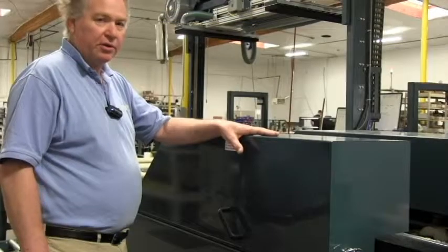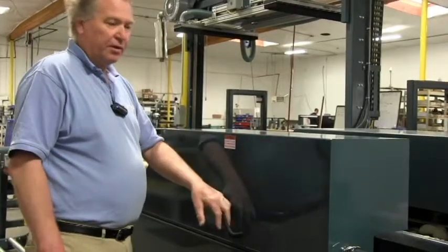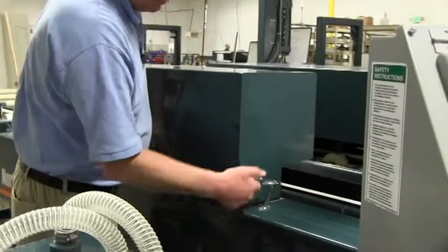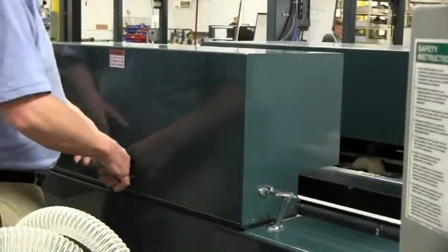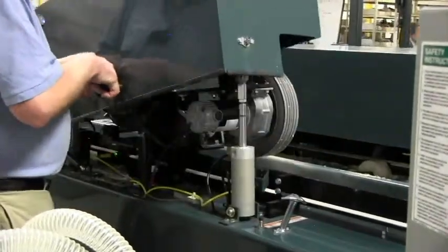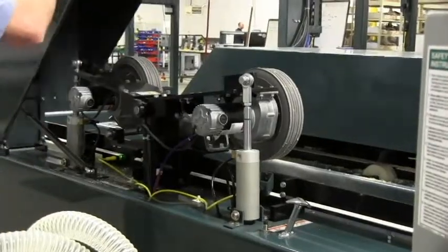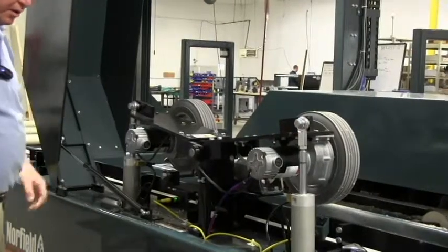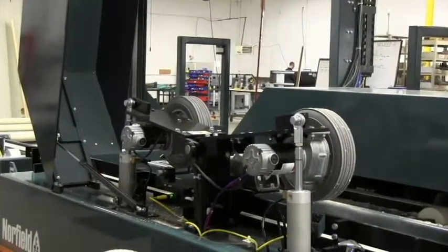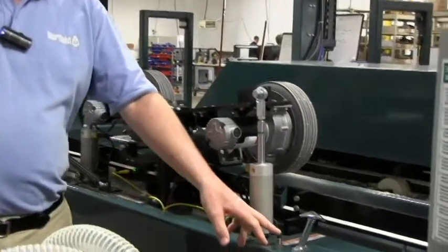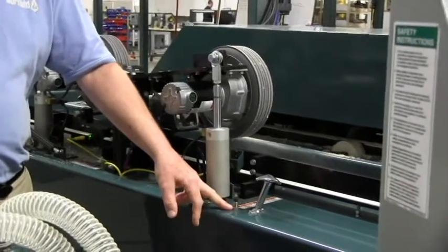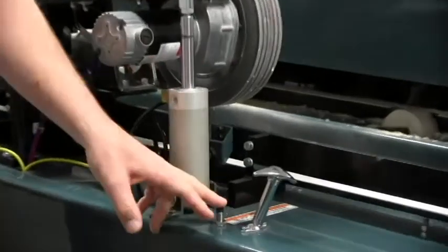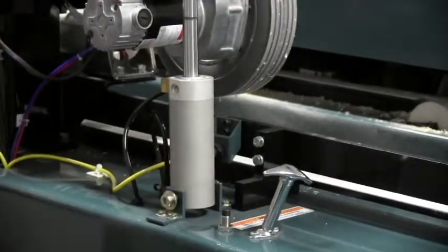You'll need to open the hoods on the Sizer. That's for cleaning or maintenance. So we're going to lift the latch at the end, raise the handle. Do not turn loose of the handle, and when it comes up so that you can position it gently at the end of the shock. There is a proximity detector here that tells the machine when the hood is closed. This machine will not operate without the hood closed and this sensing the hood.